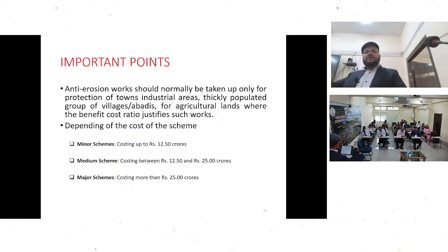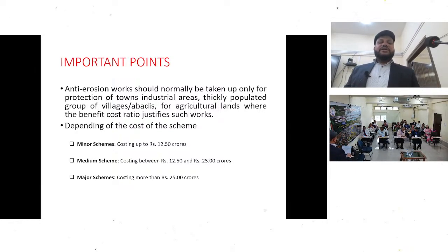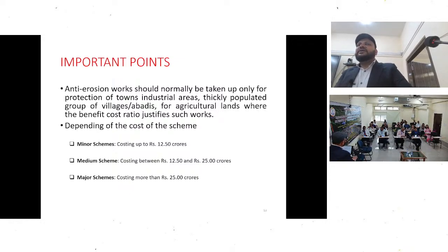It has to be like this. And technical TSC is also required. If the project is less than 12.5 crore, then the state TSC, meaning the state government TSC, is sufficient. If any project is between 12.5 and 25 crore, then it should go through the Brahmaputra Board in the Brahmaputra Basin, through GFCC in the Ganga Basin, and through the Central Water Commission in the rest of India.